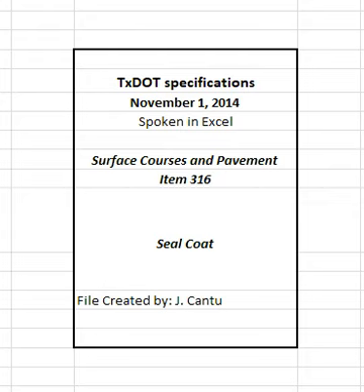4.8 Asphalt placement. 4.8.1 General. The maximum shot width is the width of the current transverse distribution test required under section 316.3.1.3.1, transverse distribution, or the width of the aggregate spreader box, whichever is less. Adjust the shot width so operations do not encroach on traffic or interfere with the traffic control plan, as directed. Use paper or other approved material at the beginning and end of each shot to construct a straight transverse joint and to prevent overlapping of the asphalt.